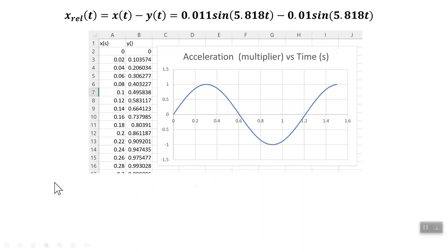Now, when we do this problem as a base excitation problem, because the motion of the mass is taking place because of the motion of the base. So it's a base excitation problem. What we need to do is basically tell the software what that acceleration of the base is. And remember, acceleration of the base was a sine function multiplied by 0.33, which was omega b squared times y. So this is my time modulation curve that I'm going to give Catia.